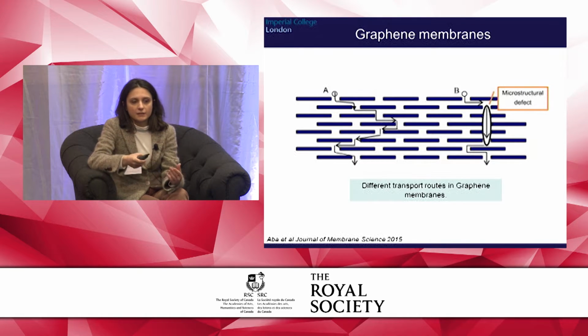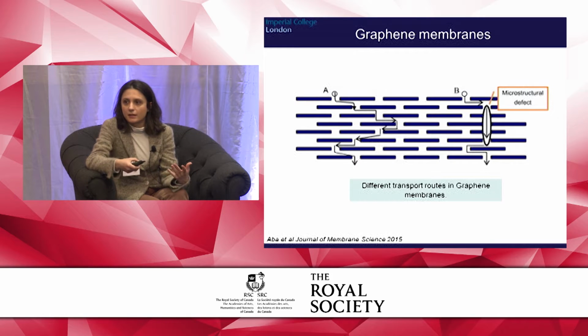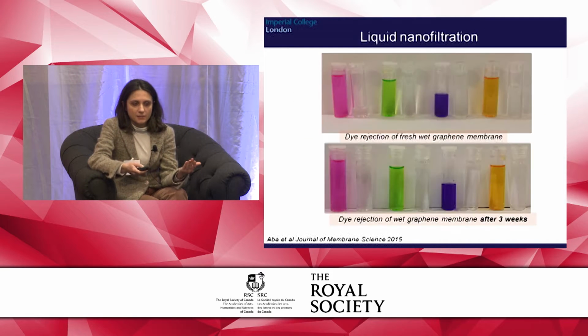And we can identify, between one layer and the other, possible paths for liquid to go through. If we control the length of this path and the distance between these layers, we can actually engineer a membrane. So we can use these thin films as selective membranes.